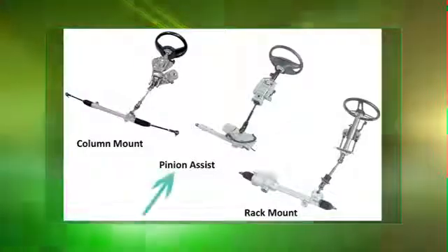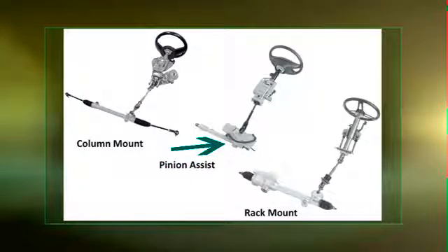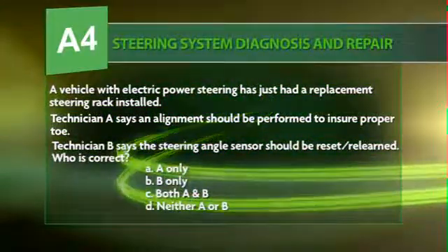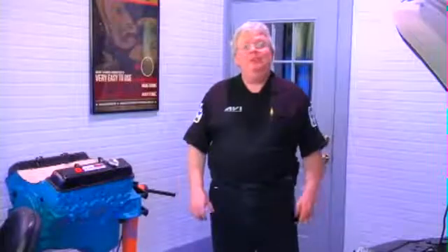So whether you've got electric power steering in any of these places or not, you put on a steering rack. That's Mr. Obvious. That's a basic mechanical common sense question. We know technician A is right. Technician B says, do I need to do a reset or relearn on the steering angle sensor? And no matter what, if you're replacing that sensor, sometimes disconnecting a battery on some cars, like Chrysler for example,